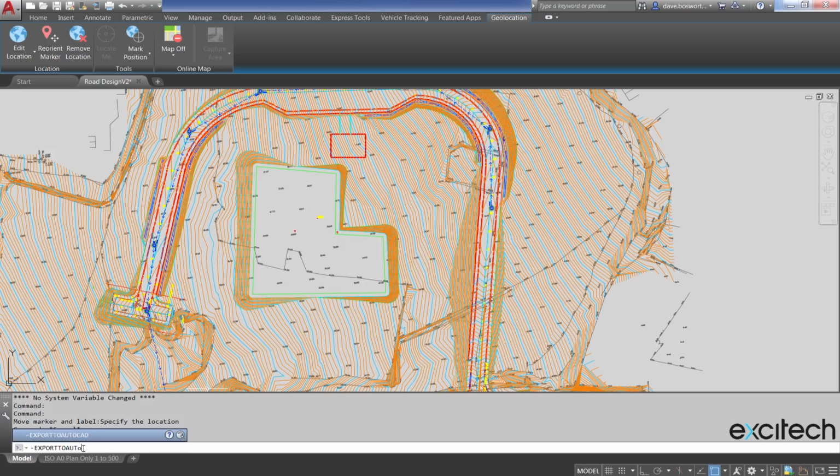This command of course also exists in Civil 3D to enable users to export a Civil 3D model to plain AutoCAD objects. Now any AutoCAD user with the Object Enabler installed can export a Civil 3D model to an AutoCAD drawing with native AutoCAD entities.